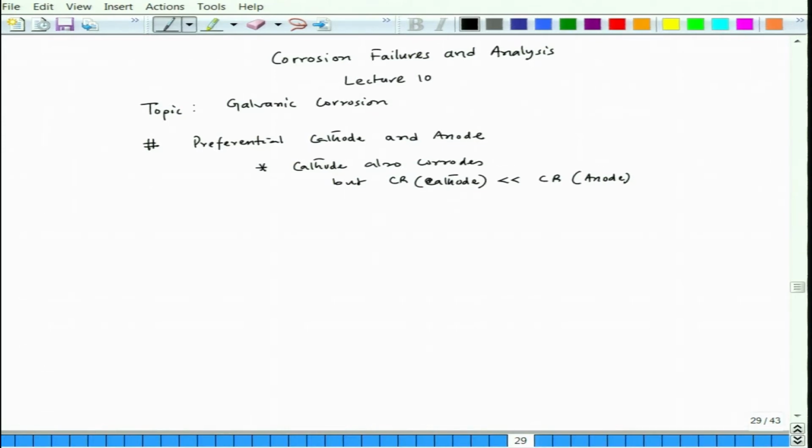So, now coming to galvanic series, we could understand how the galvanic series is made. This is basically comparing polarity of two components or two metals or alloys in a particular solution and putting the metal or alloy on top of another just by looking at the current flow in the external circuit or through the metallic conductor.